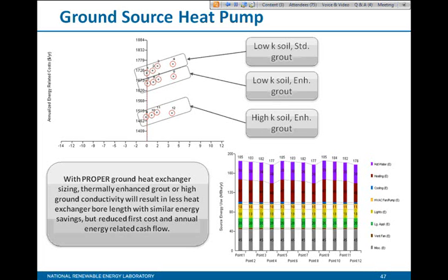Right, so if you have undersized the system, I think the first impact is in some climates, including heating-dominated climates, if you don't have an electric resistance heater, there's a potential for freezing the ground if the control is not properly done.